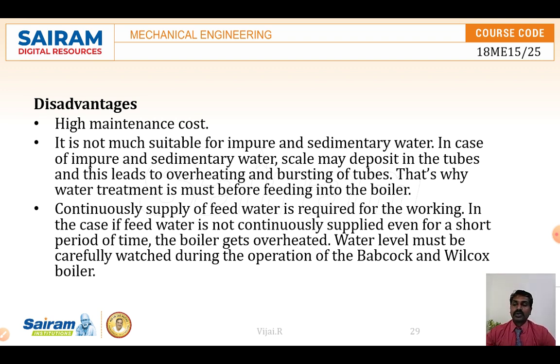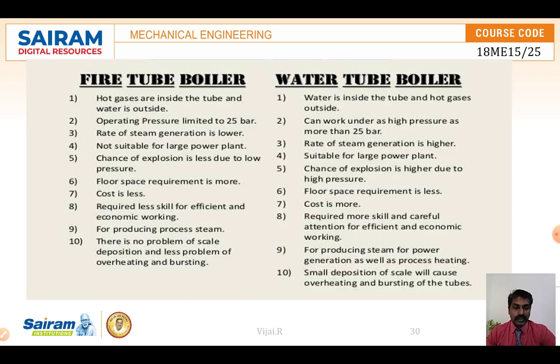Water is also not flowing properly. These are all the things that will come. So treatment is important, and the continuous supply of feed water is required. Suppose what will happen if there is a water shortage, then the boiler gets overheated.